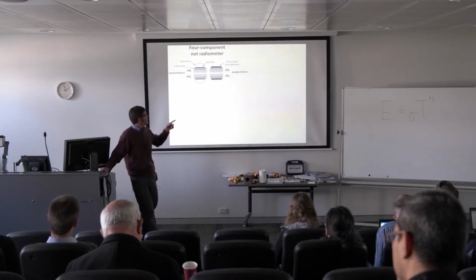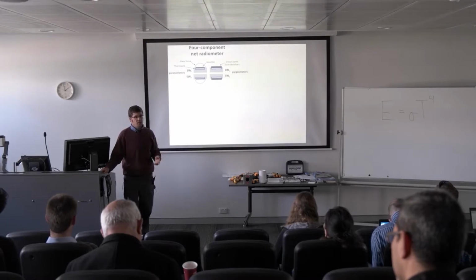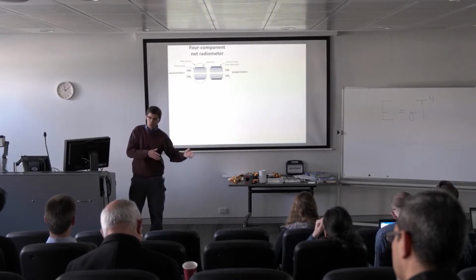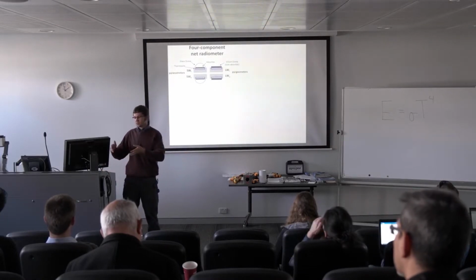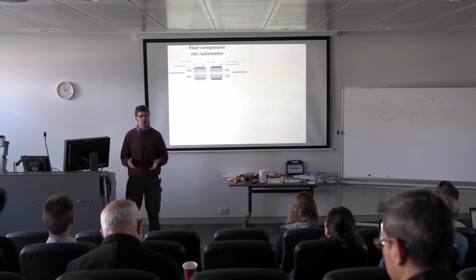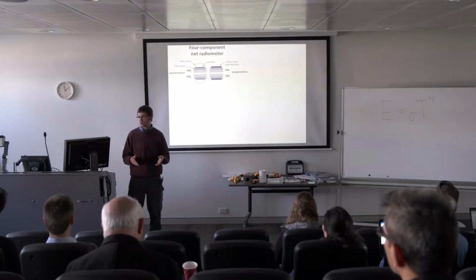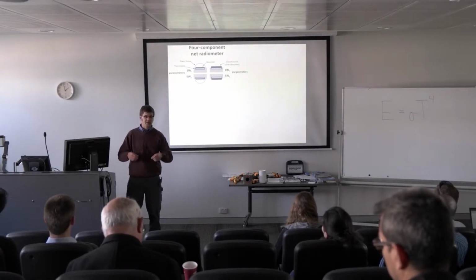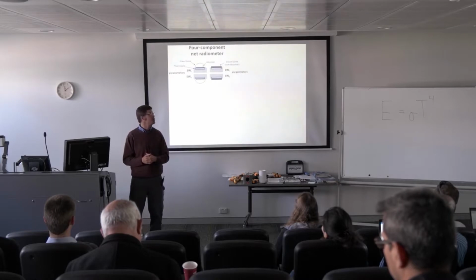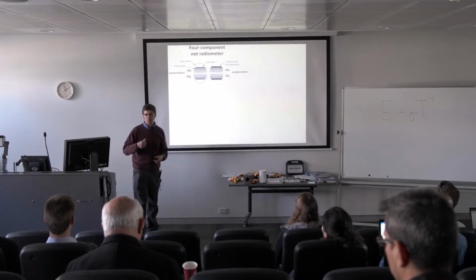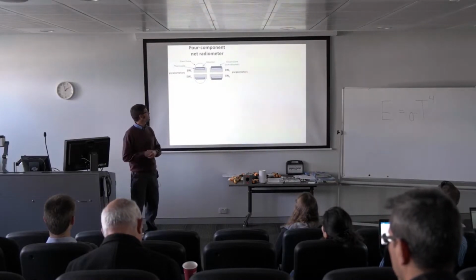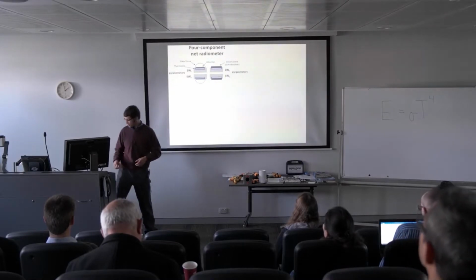And so the reason that we use a silicon dome is because it blocks the short wave radiation and transmits the long wave radiation. So a pyrgeometer is designed to measure long wave. We have to block the short wave and allow only the long wave through so that the black body absorber can absorb it and the thermopile can measure it. And so here again you've got one up, one down to measure the short and long wave.